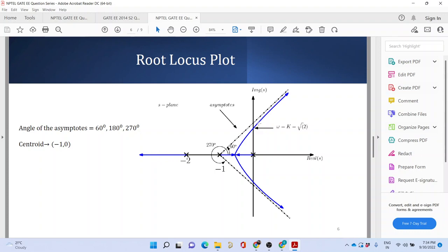It would pull this root locus towards the left hand side of the S-plane. So this will be pulled towards the left hand side of this plane. So if you pull this, the point I was making at the very first slide, this intersection will go up. So k may be higher, or it may not intersect at all, it will be asymptotic to this line. So you can easily eliminate the other two options.